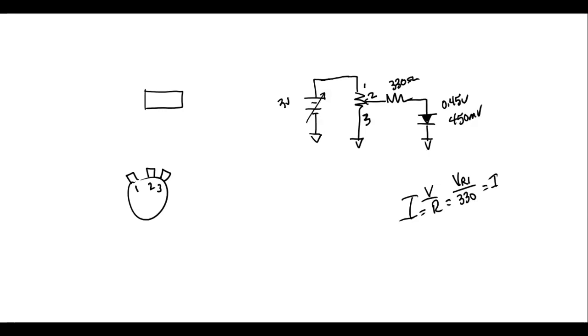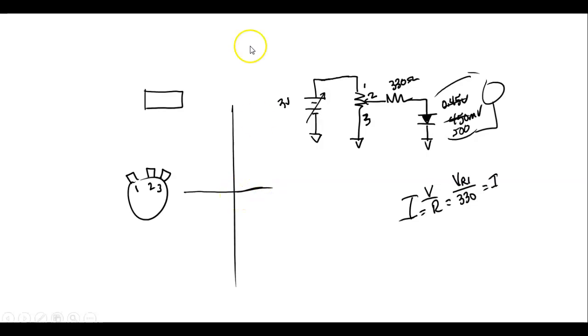And then what will we do? Once we do that, we'll adjust it up to 0.5 volts across my diode. We're going to see where it actually breaks. We're going to see where it actually starts conducting. So all we're trying to do is see where the diode starts conducting. So when I actually come up here and draw my table, which is on the next page, the page before the question, we got this graph that we're going to be working with.